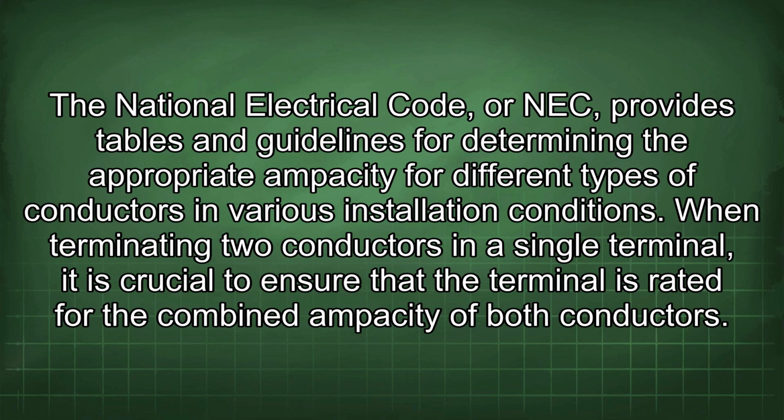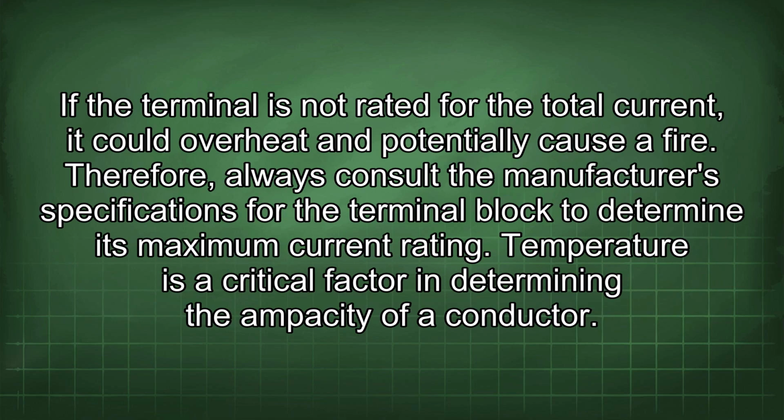and various installation conditions. When terminating two conductors in a single terminal, it is crucial to ensure that the terminal is rated for the combined ampacity of both conductors. If the terminal is not rated for the total current, it could overheat and potentially cause a fire. Therefore, always consult the manufacturer's specifications for the terminal block to determine its maximum current rating.